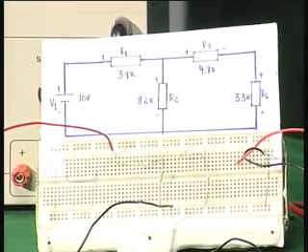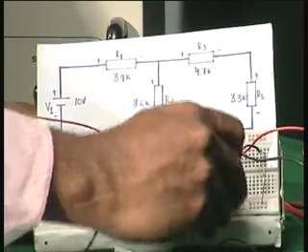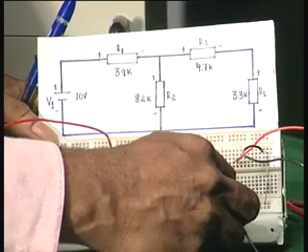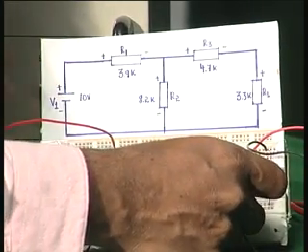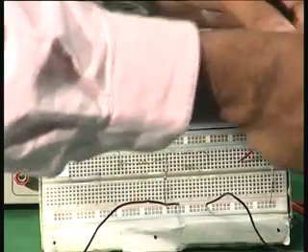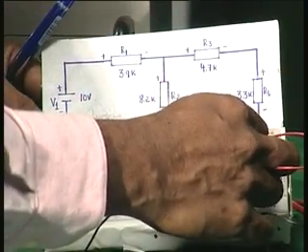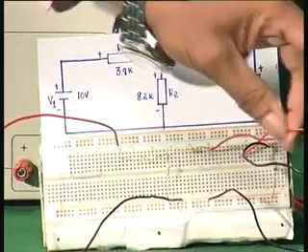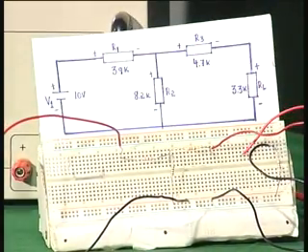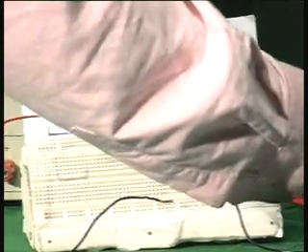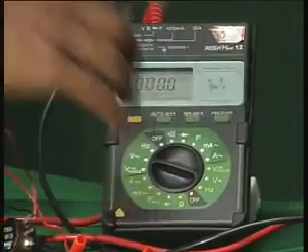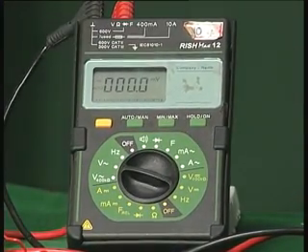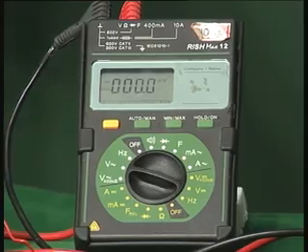Let us do that. So, for that I remove the load resistance. Therefore, under open circuit condition I have the multimeter. I will connect one end to the ground. I will take the other end and connect it to the point where R3 is coming. So, this is the multimeter. Now, I will switch on the multimeter to voltage range, put it in volts and connected to DC. Now, it is reading 0 because I have not switched on the power supply.